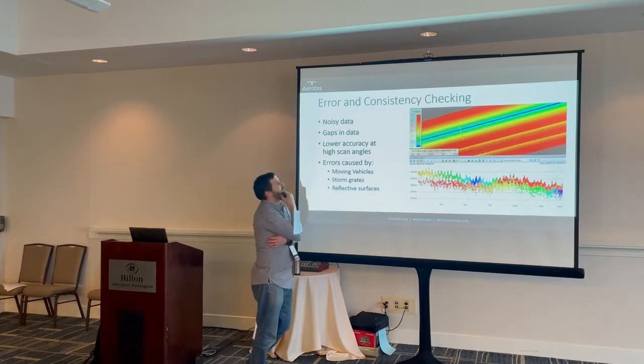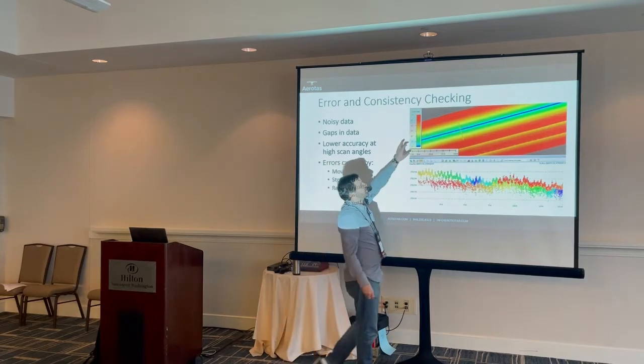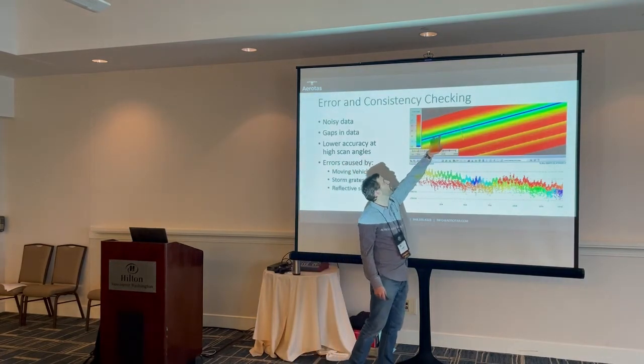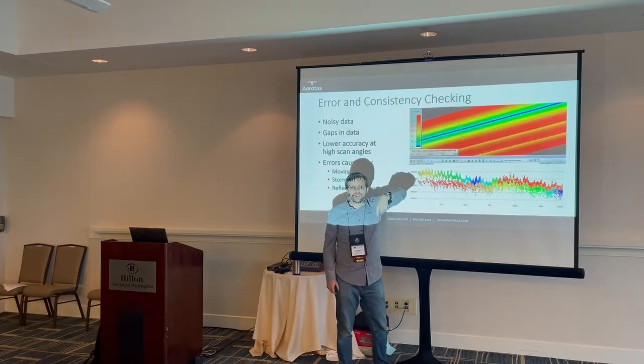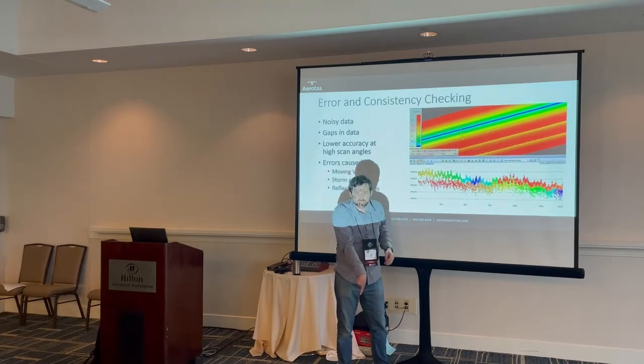This is an interesting picture that I've done. At the top, this is looking top down, and the points are colorized by scan angle. So these blue points in the middle, that's looking straight down along the path of the drone, where the LiDAR sensor was pointing straight down.